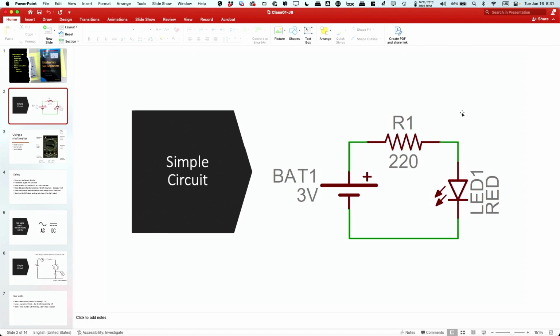The resistor actually doesn't matter which direction you put it in. But some of them do. For example, the LED: what does LED stand for? Right, it's a diode. And what is a diode? Yeah, Anton: it restricts the current to one direction. Right, it's essentially a one-way valve, if you will. If you imagine current being like water flowing through a pipe, imagine a little flap that, if the current's trying to go backwards, it can't, but it can go forwards. So a diode sort of does that.